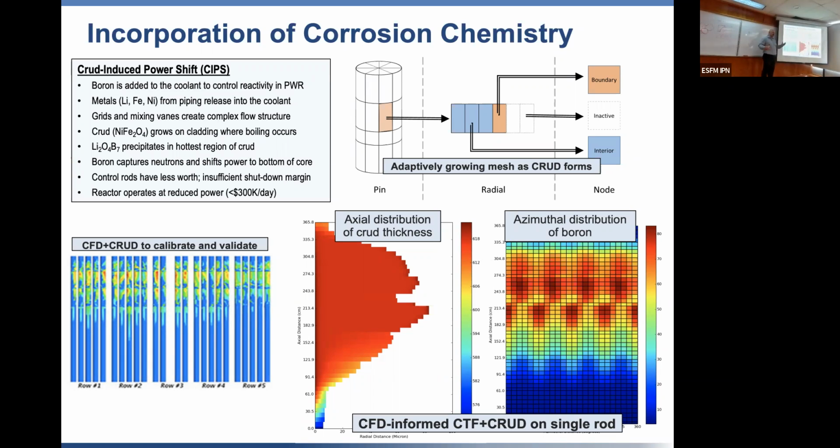So they'd always say, okay, I'm going to have to take the average rod and just increase its temperature by 20%, just so that I can be conservative. And then I tell everybody this is how you design a reactor fuel loading scheme so that you don't have axial crud growth and axial power shift because of the crud growth.